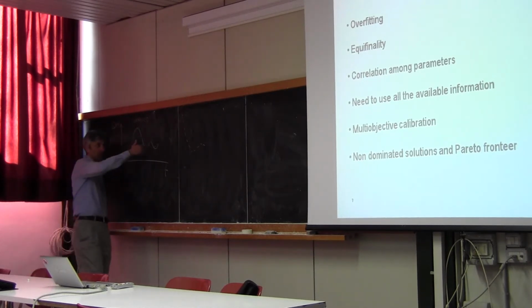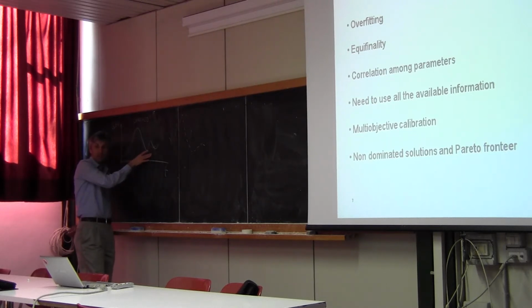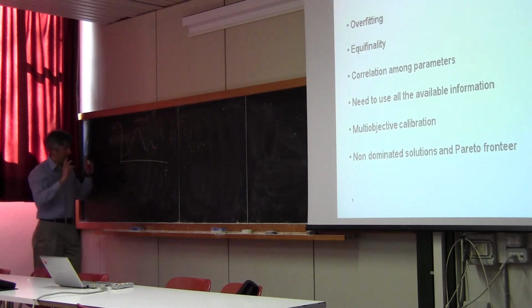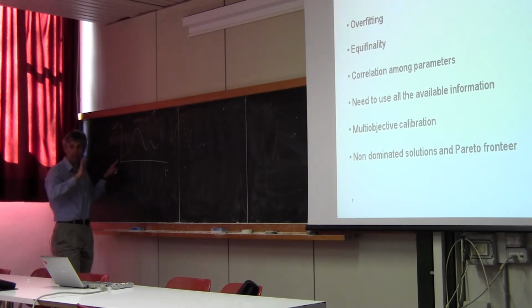By using, for instance, rainfall data that you have observed for a period for which you didn't observe the river discharge data. So you are extrapolating the parameter values that you calibrated in a period for which observations were fully available. And if you have two parameter vectors that give you similar performances in interpolation, they may provide very different hydrographs in extrapolation, because extrapolation is something much different.